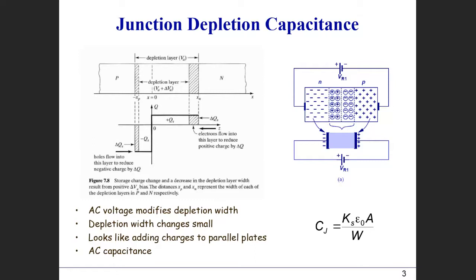So first, the junction capacitance, or the junction depletion capacitance. The basic concept of this capacitance comes from the depletion region. When you look at the depletion region in the PN junction diode, electron and hole mobile carriers start to recombine. So they leave ionized charges within this depletion region. On the P side, holes move to the N side, which leaves negative ionized charge. Similarly, on the N side, electrons move and recombine, which leaves positive ionized charge within the depletion region.